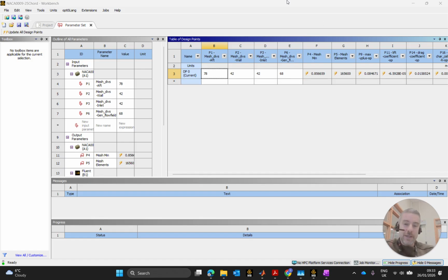So in the mesh independence study, I'm going to use the grid convergence index method. Now there's a couple of caveats with this method. This is the method that is preferred, especially for publication standards. There are other ways of doing mesh independence, and amongst them is looking at a variable of interest and refining a mesh over and over and making sure, number one, that we are converging towards a certain limiting value, and that in every subsequent mesh refinement, the change in that variable is also shrinking.